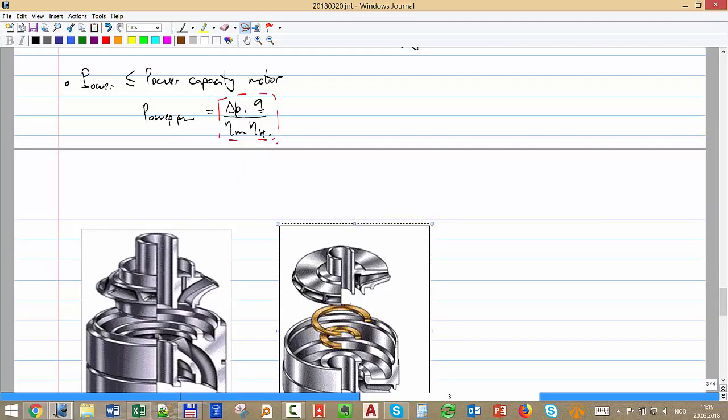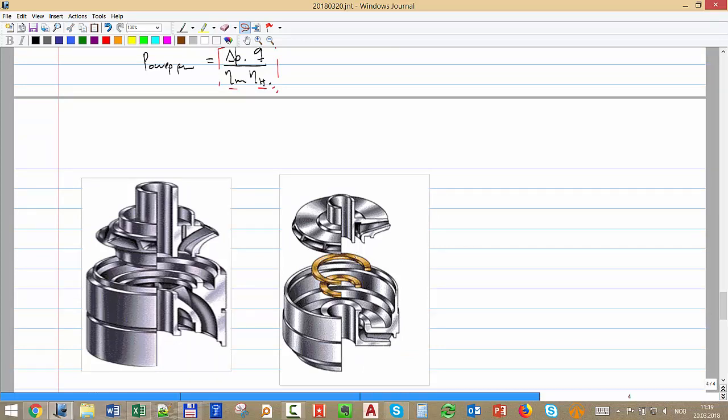for a different design. You see here how the flow enters and then goes almost completely radially. That gives you a very nice pressure increase per stage, but it's very bad for gas. If you have gas and liquid and a sudden change of direction, the liquid will go on one side and the gas on another, just because they have different densities. That creates separation in the machine, and you stop having a nice mixture; you have two phases that the machine was not designed for.